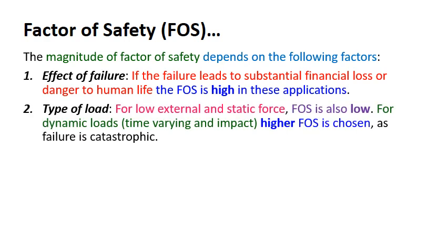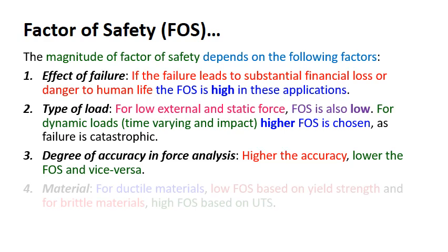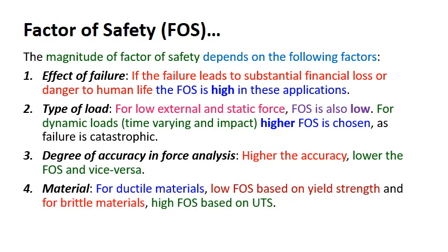Type of the load. If you have a static force, the load application will be very gradual, slow, so you can choose a small FOS. Dynamic loads, the after effects will be very dangerous, so we will select higher FOS. Degree of accuracy in force analysis. If you know exactly what the force is, then you don't need to use a higher FOS. Similarly, material.